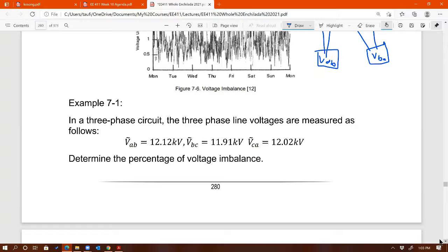And that could be a problem with the RMS value. I'll explain later, maybe not today, on Thursday, that when you have harmonics in the system due to power electronics, for example, then it's going to be different for you to calculate RMS, right? The RMS that you're getting could be higher than the nominal value because of harmonics, right?